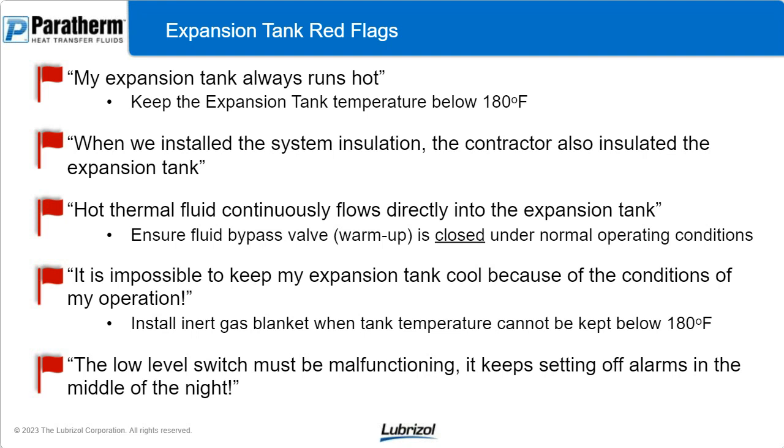There is a switch, usually some kind of a mechanical switch, a plumb bob or something, a plunger in your expansion tank, a float switch that's going to measure the level. And if the fluid level in the expansion tank goes too low, that's going to create a lot of flow problems. It's going to create overheating and a lot of issues. We talked about how important flow is. If you don't have adequate fluid volume, you're not going to have adequate flow.